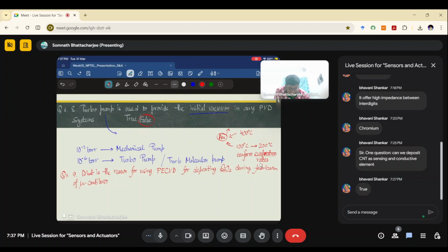There are other ways, right? CVD means chemical vapor deposition, right? At low temperature, yes, for low temperature. So what temperature does it work at, can we deposit silicon dioxide? No, silicon dioxide requires high temperature deposition, right? Yeah, so the question is why do we need to use PECVD? Through using PECVD, we can deposit at a very low temperature. So that's the right answer.